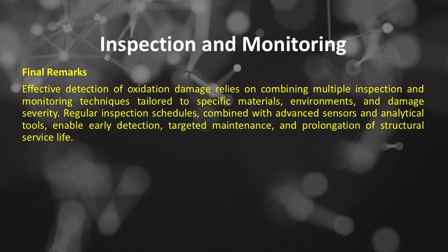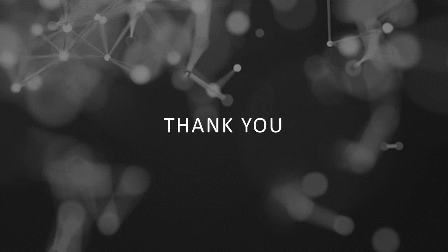Final remarks. Effective detection of oxidation damage relies on combining multiple inspection and monitoring techniques tailored to specific materials, environments, and damage severity. Regular inspection schedules, combined with advanced sensors and analytical tools, enable early detection, targeted maintenance, and prolongation of structural service life.